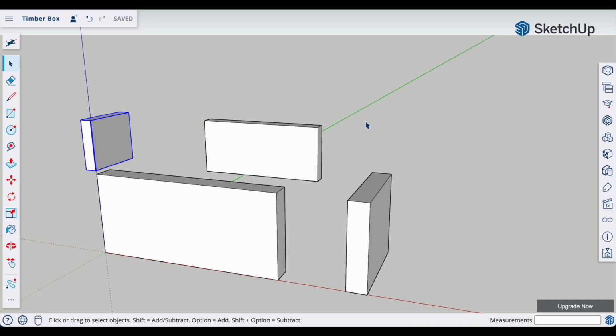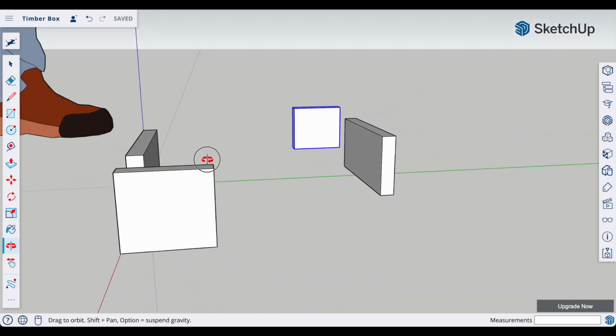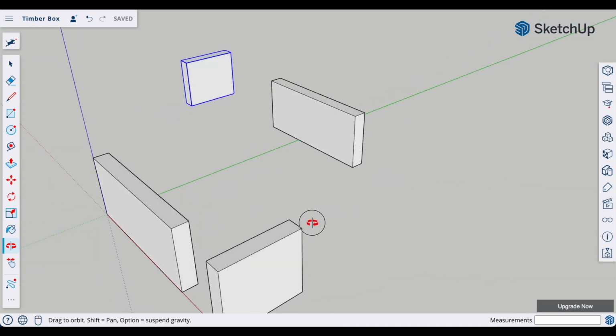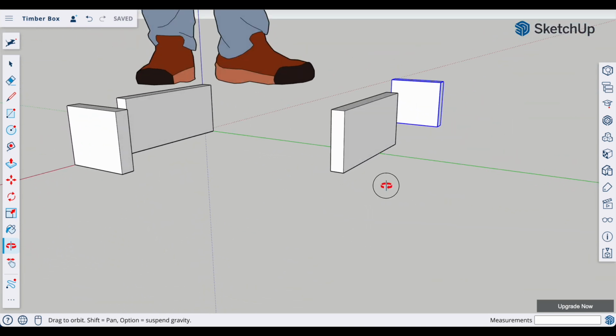Okay, a couple other tools when it comes to navigating your screen. And these are really important to ease the frustration when you're trying to see the shapes from a specific angle. If you move down your toolbar here, and I'll also call out the shortcuts as we get to them. This tool here called the orbit tool, and you can see the shortcut is O. Now what that allows us to do is, if I click and hold and then slide around my trackpad, it allows us to rotate and move around that shape in 3D.